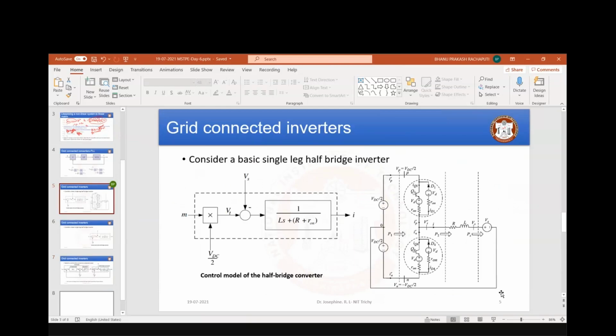Then you have to have the state space representation of your motor, and a specific output Y. Here, this converter you have to take as a first order differential equation, just this converter, like you'll get e power minus Ts, as I said. Why do they take only a first order differential equation? In steady state, any plant can be realized using first order. You don't need any complexity. And even in industry, to tune the parameters, they don't want a complex network to control.